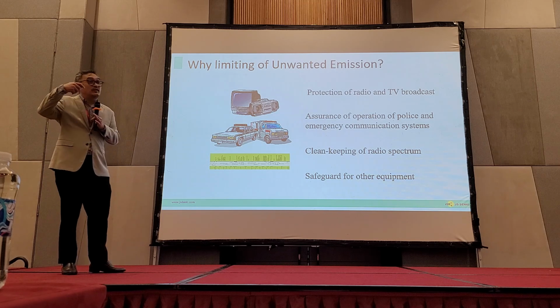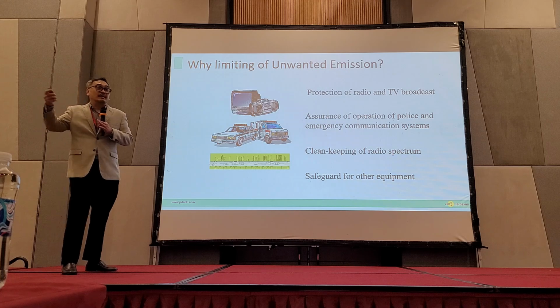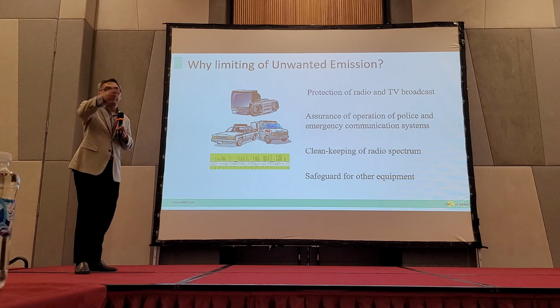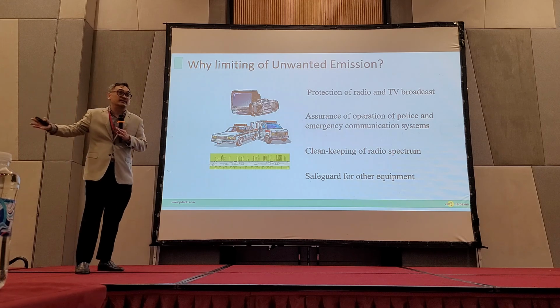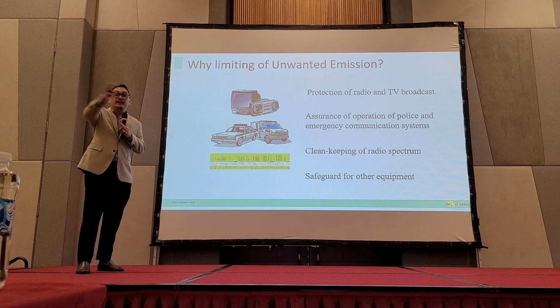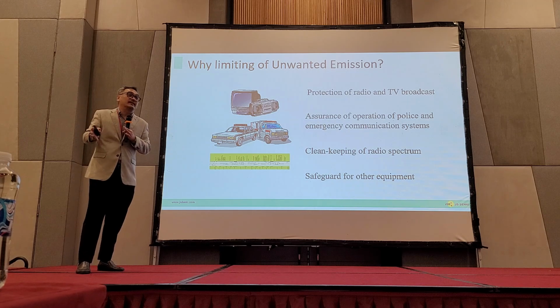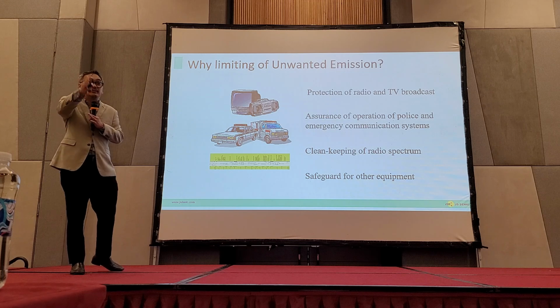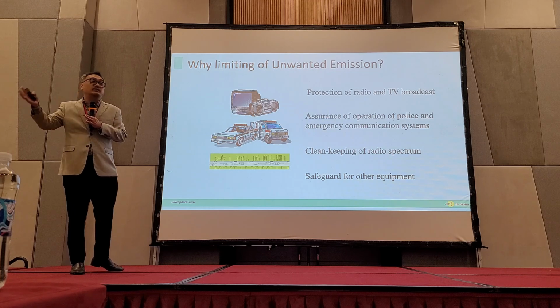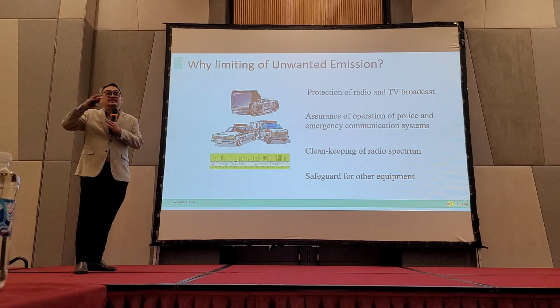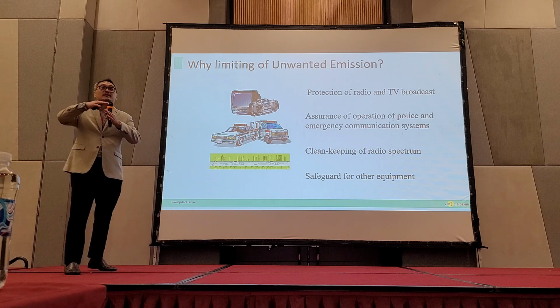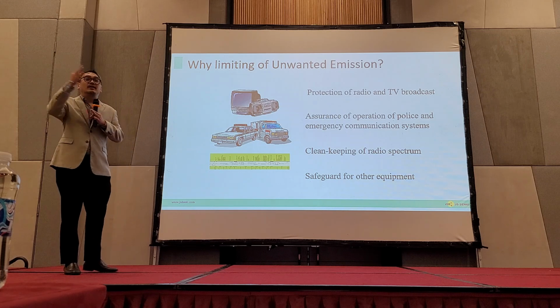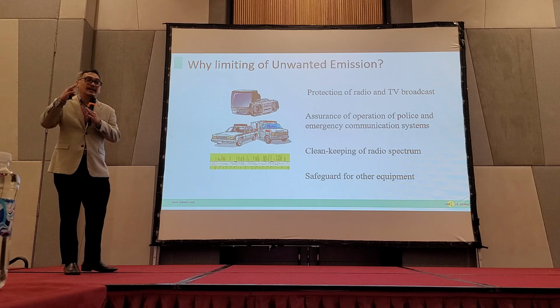But when you have noise, for example, the noise of a product like a projector is at 900 megahertz. It's very high. Nobody here will get telephone signal in the GSM because the noise at 900 meg is very high in the projector. So everybody will be cut off from the signal. This is something that we don't want. It makes the RF system haywire.